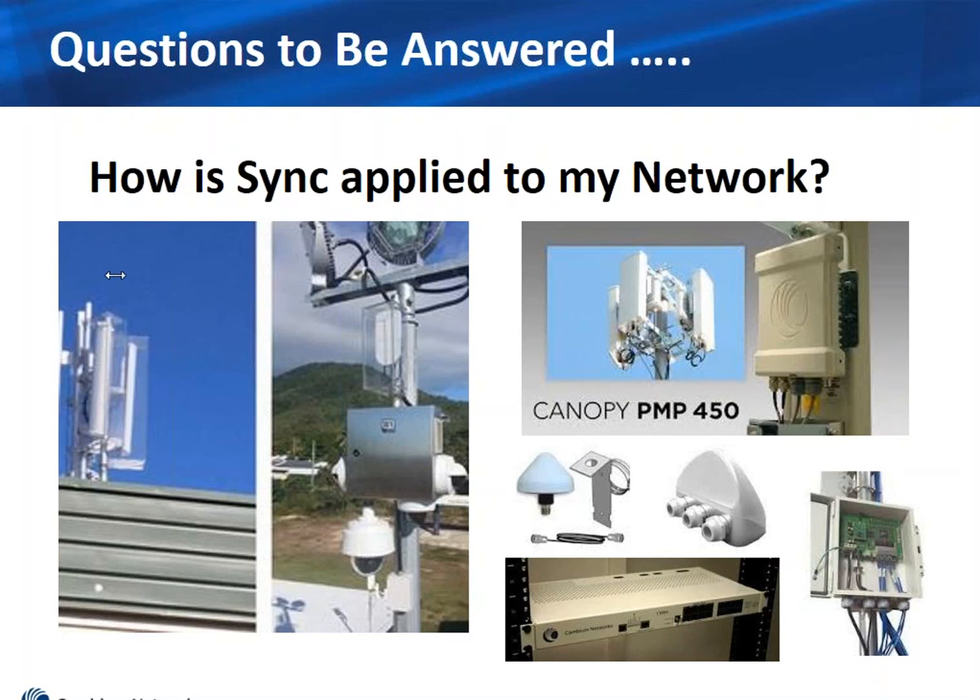If you have a temporary loss of GPS, allow it to free run for just a little bit of time and then eventually determine whether you want it to shut off or if you want it to keep running. There's various different flexible options for how the access point can run based on what GPS you've selected and is that GPS available, meaning an external GPS or an internal GPS or something coming from the sync port or just using internal timing. Hopefully that answered the question.